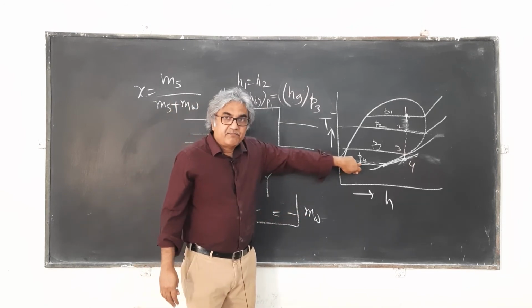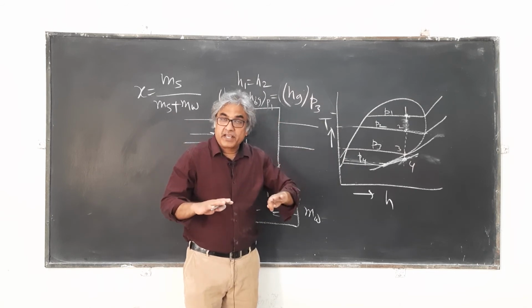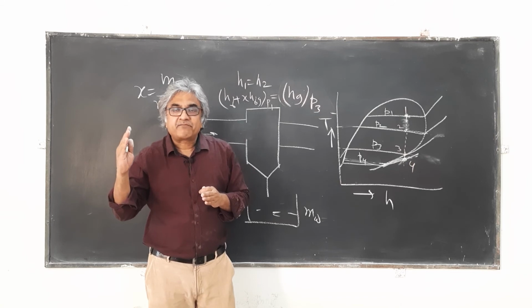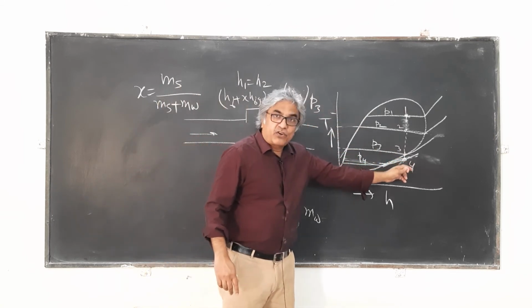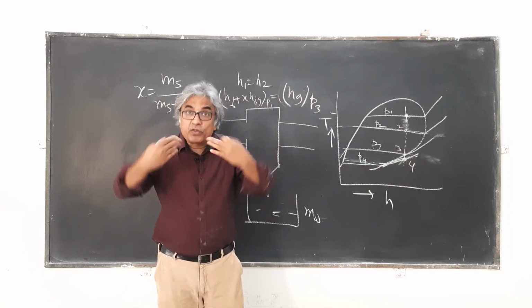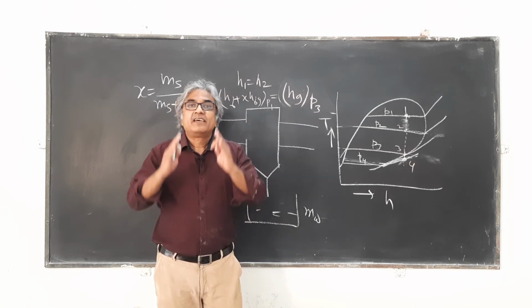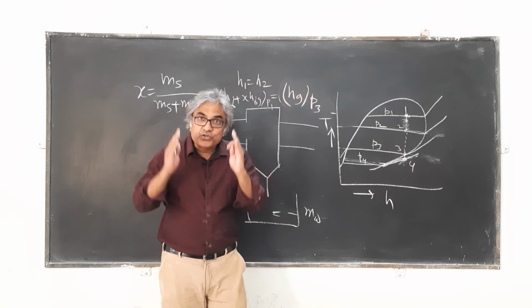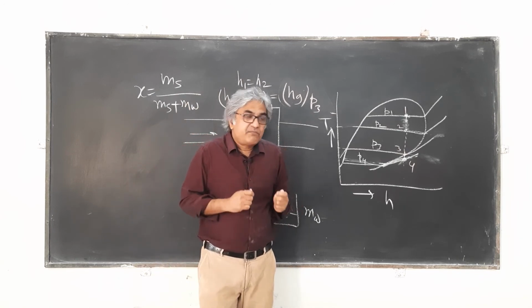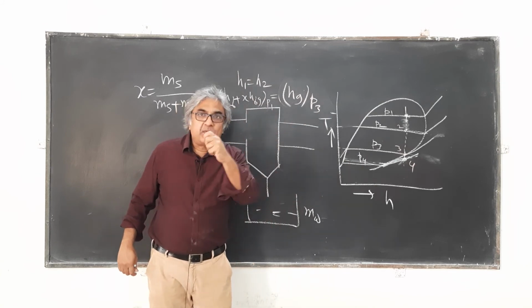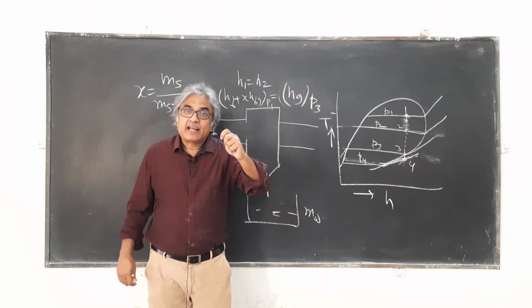You know the pressure after the throttling. See what the saturation temperature corresponding to that pressure is, and if the actual temperature of steam after throttling is more than the saturation temperature, then you know that the steam is superheated. You can't be sure that the steam is dry saturated, because the temperature is common for wet steam as well as dry saturated steam.